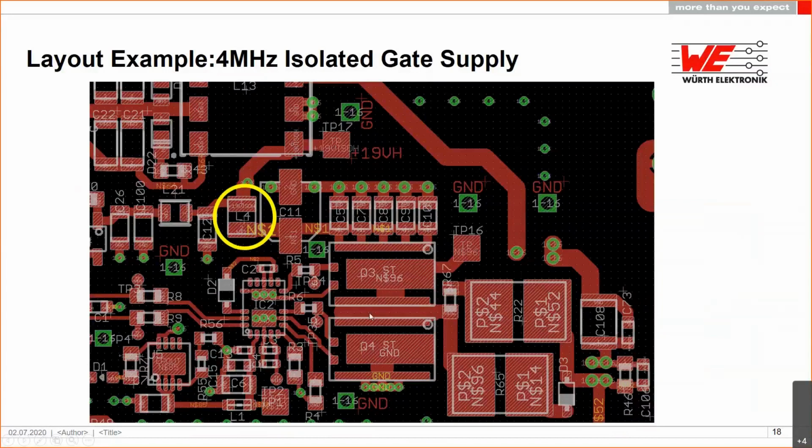Then we have the high side GaN FET and the low side GaN FET. These are both connected very close together, only 0.5 millimeter distance between them, and the gate drive is very small in length. We have 0402 resistors here with only 1-2 millimeter distance to the GaNs, and after the GaNs, we go to the gate drive resistors, and then we go more to the SiC devices.